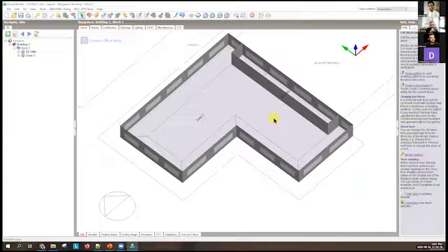If you can condition them with separate systems, you can maintain comfort in each of the zones. If you don't separate them into perimeter and center zones, then when you do a load calculation, it's a really big average across the floor plate, and everybody's uncomfortable at all times. Why do I say that?